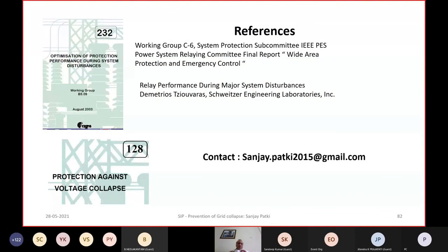Sir, I have a question. In case of a three single-phase transformer bank, we do not have the restricted earth fault protection. We are having only differential protection, and the CTs are located inside the delta. But the thing is, the zero sequence filtering is enabled in both the H and L side. So in that case, earth fault sensitivity will be less for differential. So what can be done to increase the earth fault sensitivity, because there is no REF protection in that?